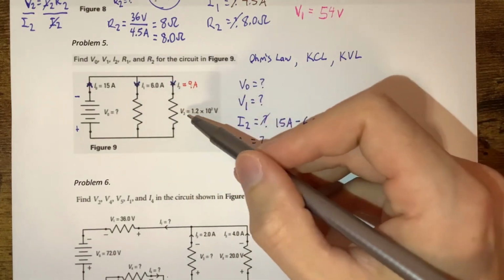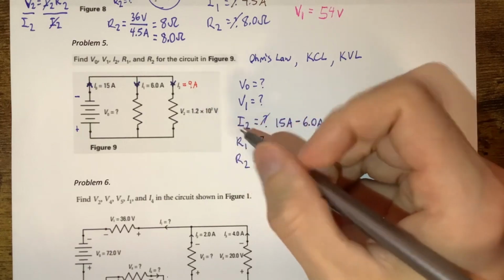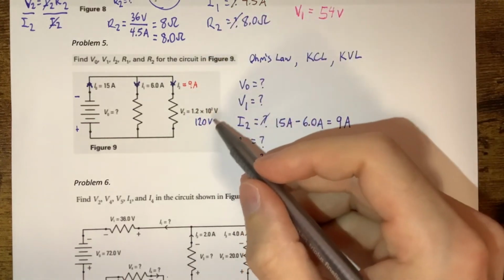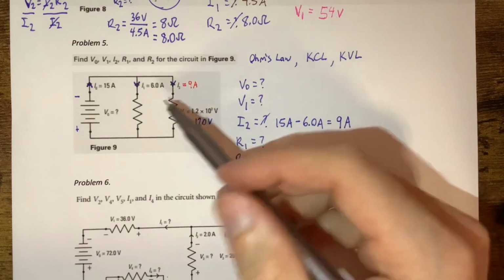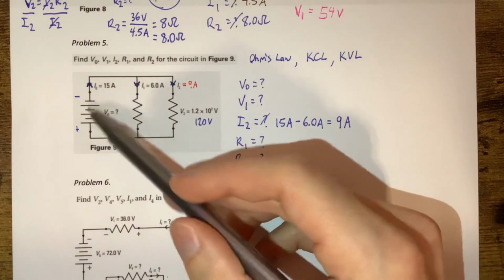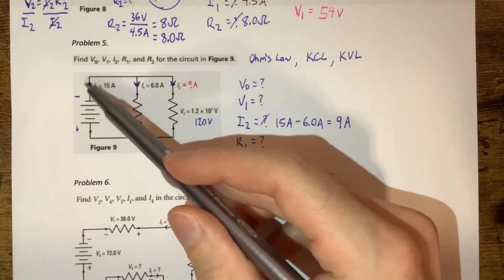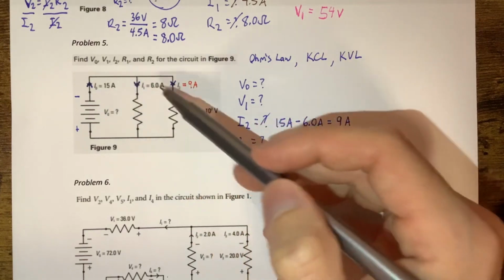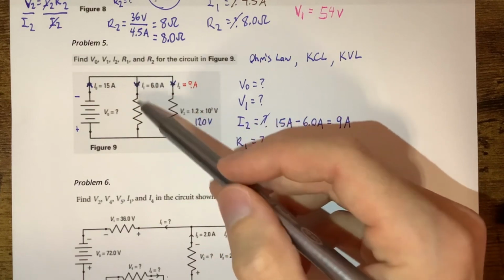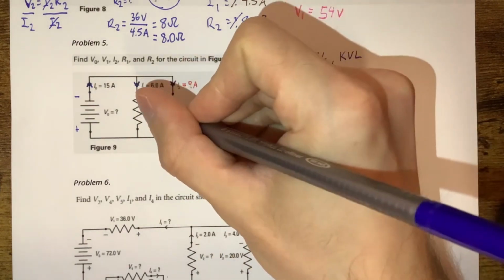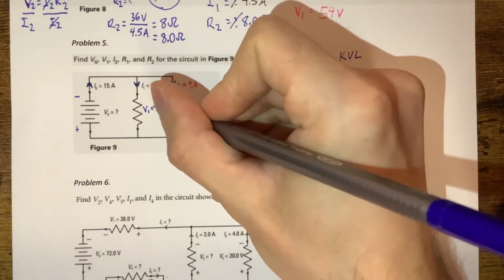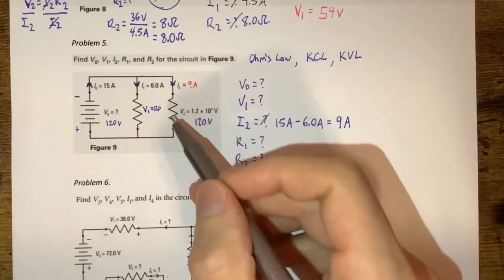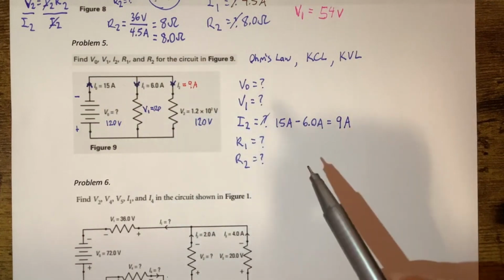So in other words, if this is our V2 here, this is 1.2 times 10 to the 2. We can put that in regular numbers instead of scientific notation. That's 120 volts, okay? So if this is at 120 volts over here, that means that this battery brought all those electrons up to 120 volts at the beginning, okay? Because these water slides, these lines here, are essentially at the same level, okay? So that means that this V1 also has to be 120, and this V naught here also has to be 120, okay? And this is what happens with a parallel circuit here, okay?